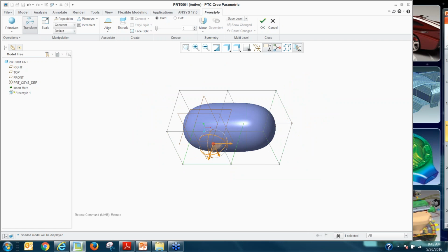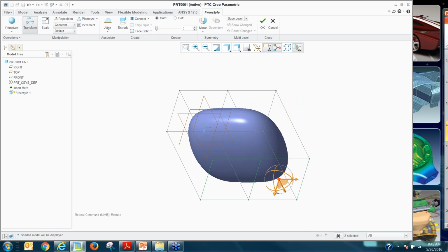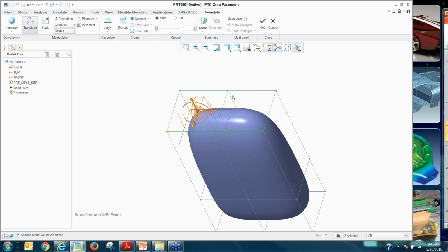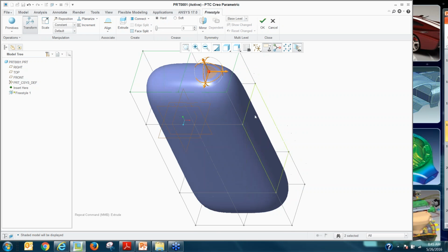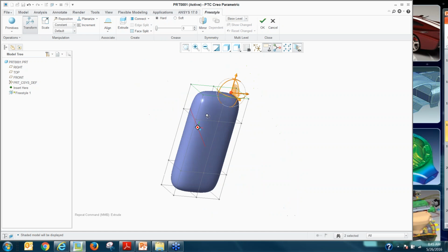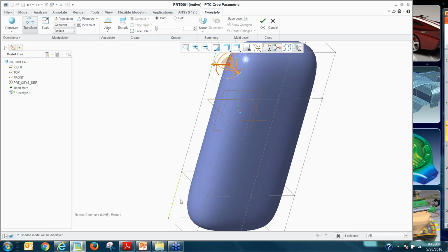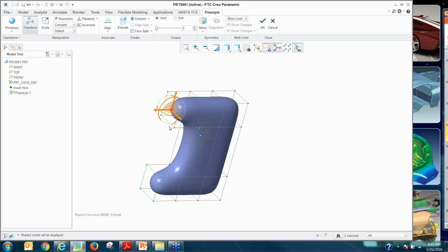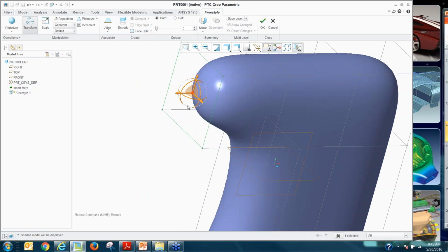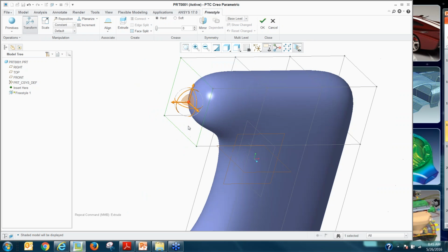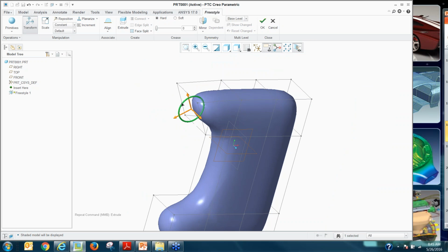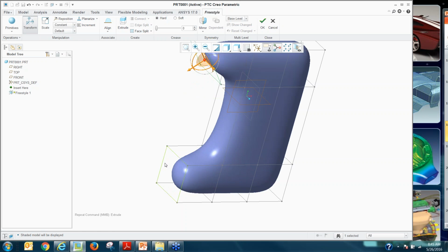So I can add, for example, I want to pull that here somewhere like that. I want to probably extrude that now. I probably want to just repeat that command, middle click here to repeat, right? And maybe I might want to just select these and again do an extrude. I can tweak individually, right? So for example, I want to just select this surface patch. I'm just using those, and I can control the resolution of this mesh, right? I can do that also.